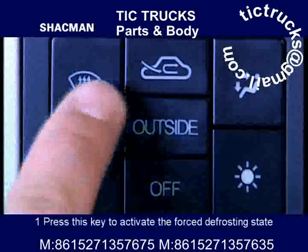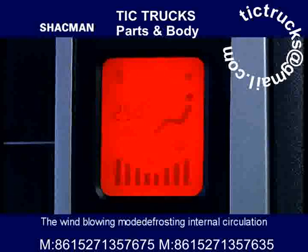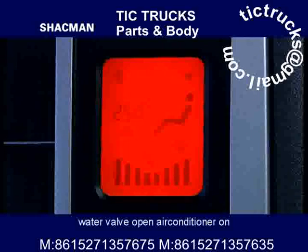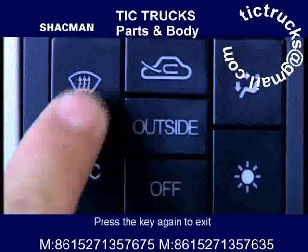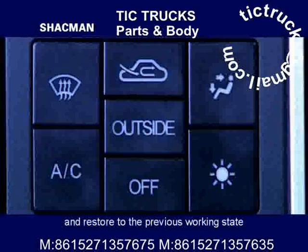Defrosting key. 1. Press this key to activate the forced defrosting state. The wind blowing mode: defrosting. Internal circulation. Wind rate at step 4. Water valve open. Air conditioner on, and the blending door in hot state. Press the key again to exit and restore to the previous working state.